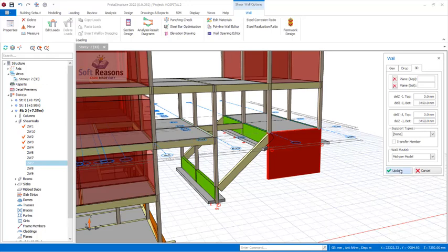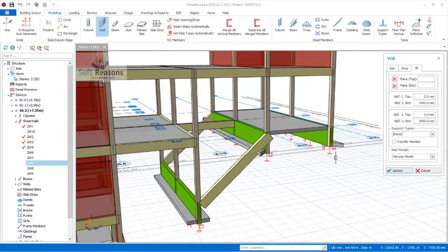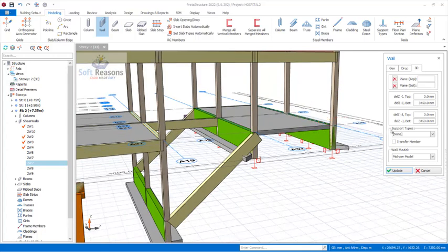So once you click on update, this will reduce this to this extent. You are no longer seeing the shear wall because the total length of the shear wall is this length. So what you now have to do is just apply the support. Once you apply the support, the shear wall will reflect and assume the depth of the foundations, because now we have support as none right there. So click in the provisions, apply support 1 right there and click on update.